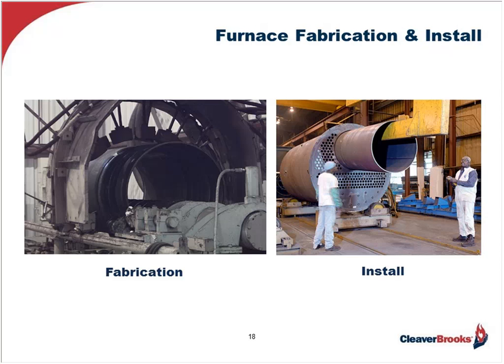Now, simultaneous with these operations, the furnace is being constructed, which includes rolling and welding of a flat steel plate again, and possibly also corrugating it, depending on the specific conditions. And I'll get into that a little bit later. Now, completing this operation, the furnace is then installed and welded into the pressure vessel, the install portion of which you see on the screen now on the right.